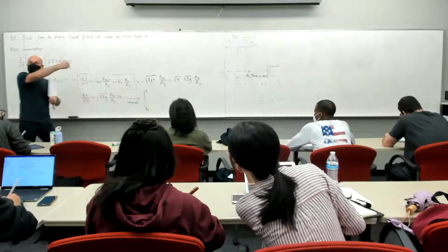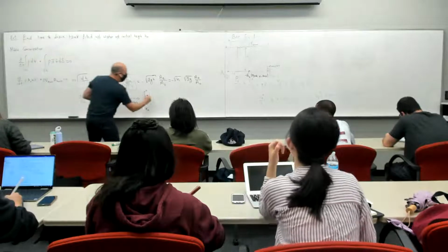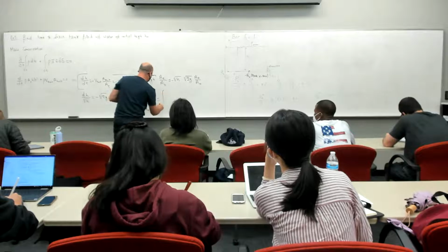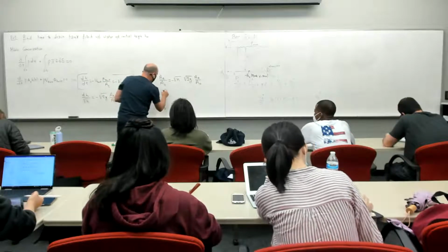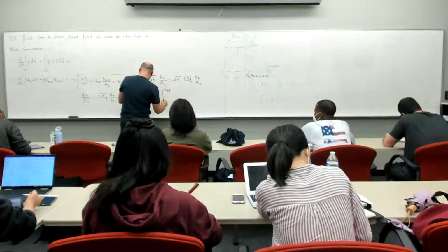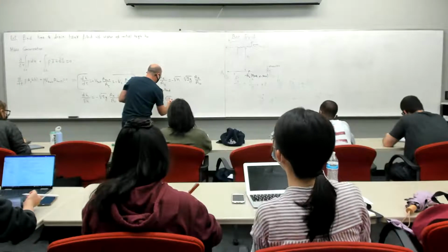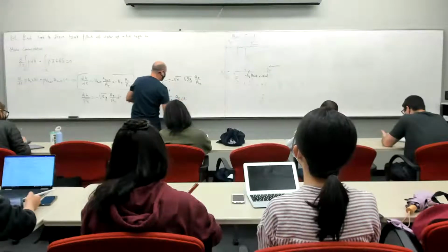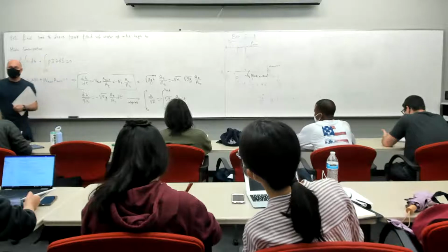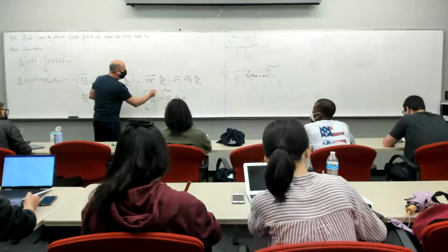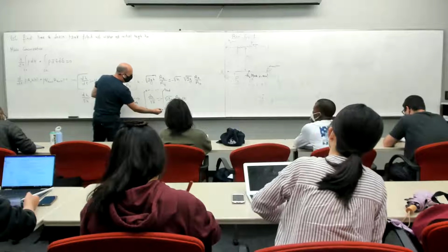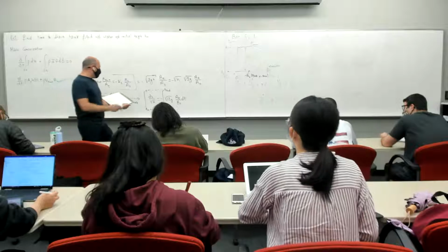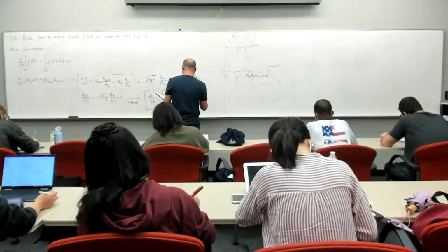So we're integrating from h0 to 0 of dh over square root of h, equal to the integral from 0 to t end of minus square root of 2g A exit over A tank dt. So now you see where t end showed up. If you notice, t end corresponds to a height equals 0, and t0 corresponds to a height of h0. You do the integral.